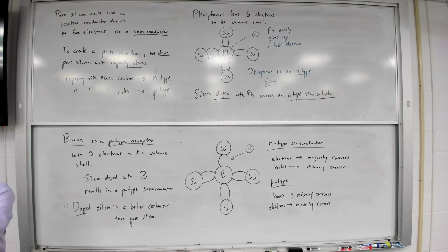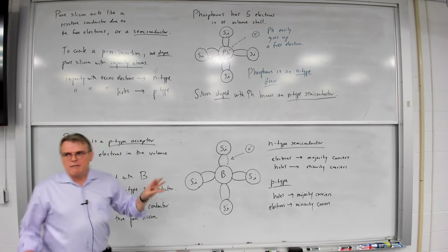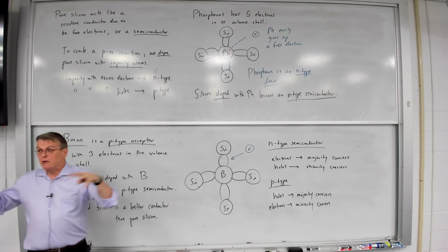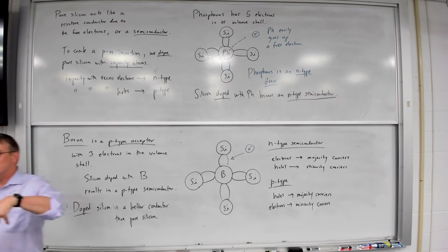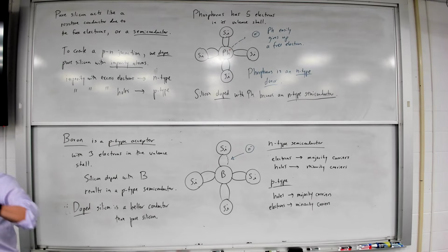And assuming that any flow out of the semiconductor, they're going to be replaced by others flowing in. But you're always going to have that certain level of excess holes just because, once again, the phosphorus atoms, for example, don't want them back. And so you're always going to have that level in there. This is really all balanced out by the thermal energy going on. So you're always going to have these electrons popping loose and staying loose because of thermal energy.